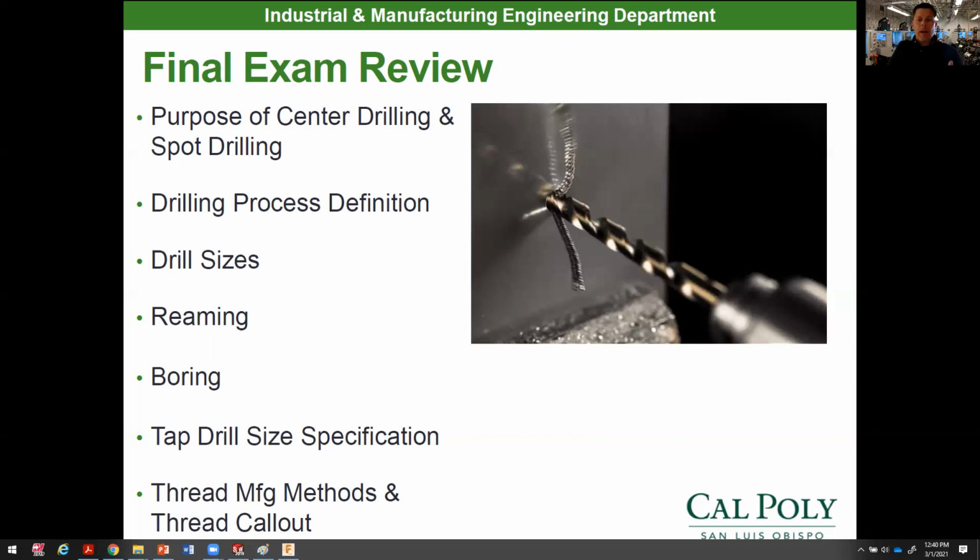So I would know some thread manufacturing methods and know how the thread call out works for these methods. I might give you a thread call out. On that thread call out, you're going to tell me if it's an A or a B thread, external or internal thread, and how I'm going to manufacture that thread. You also might have to tell me what the pitch is of that thread, or the distance that it's going to travel for 1 revolution of that screw thread. So I would know how to calculate the pitch off of a thread call out.